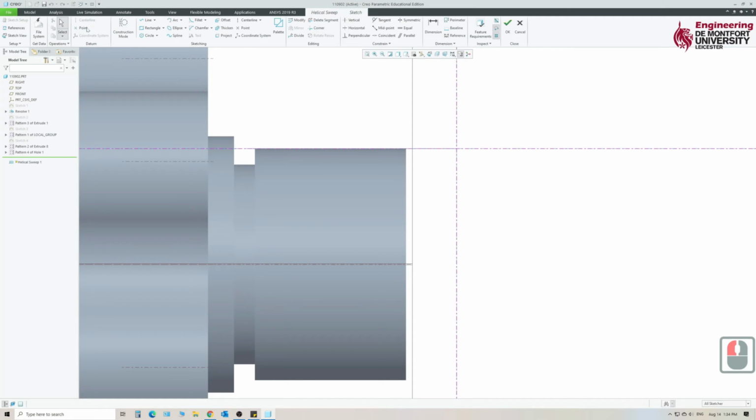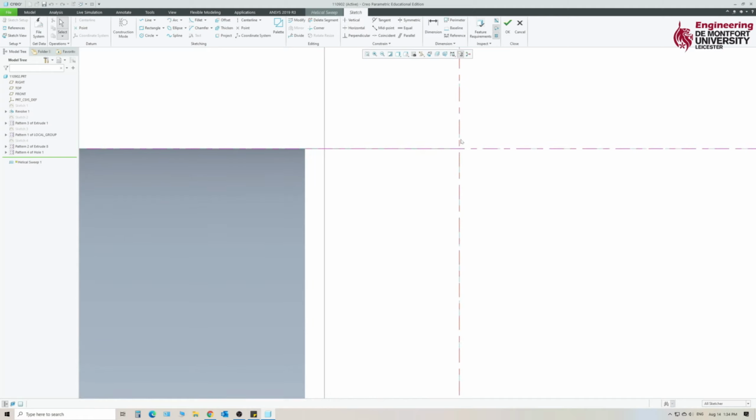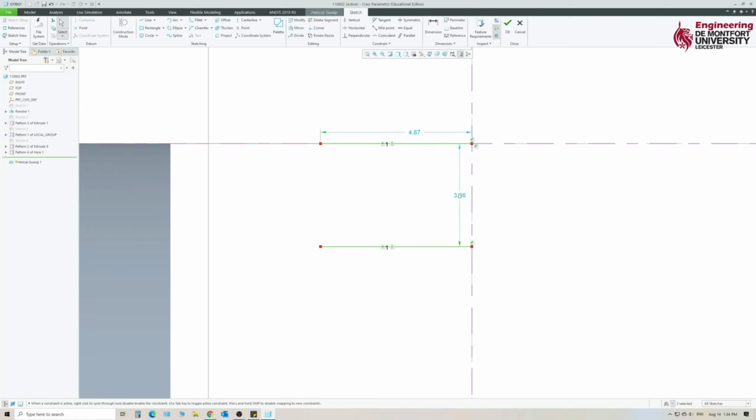And now if we go sketch, this is where we sketch our geometry for making the cut. And we can see we've got some reference lines showing us where our cut will start from. So let's draw the thread geometry and draw a line along the top, line along the bottom. Set the separation to 2.76. And then let's draw our V shape.